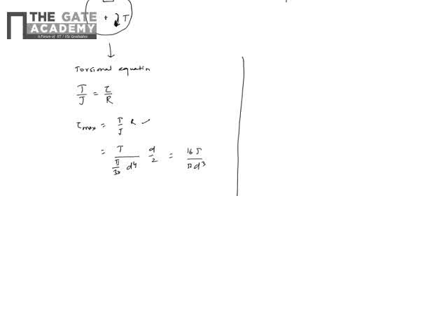Now when a torque T is acting, this part acts on this part. So basically, if I consider only the key portion, the equivalent force because of this torque is basically T by d, because force into d is the moment, and the resisting force from the hub is F. So basically it is shear along this plane.